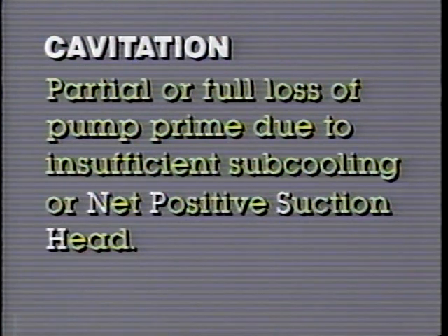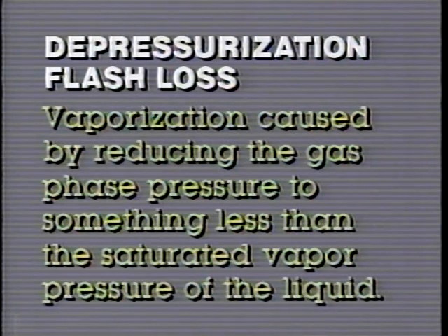Cavitation, partial or full loss of pump prime due to insufficient subcooling or net positive suction head. Depressurization flash loss, vaporization caused by reducing the gas phase pressure to something less than the saturated vapor pressure of the liquid.